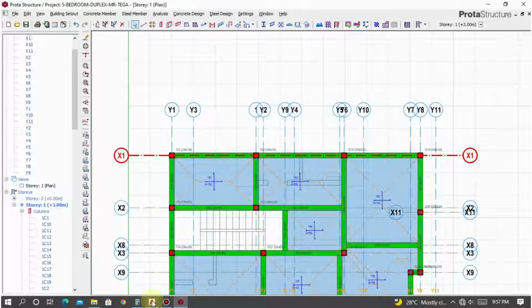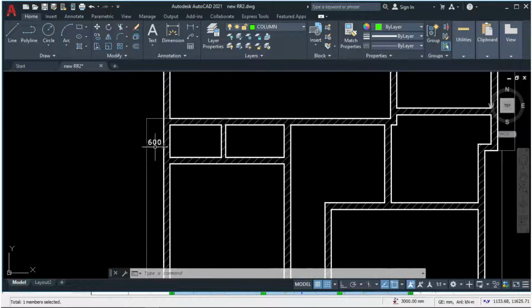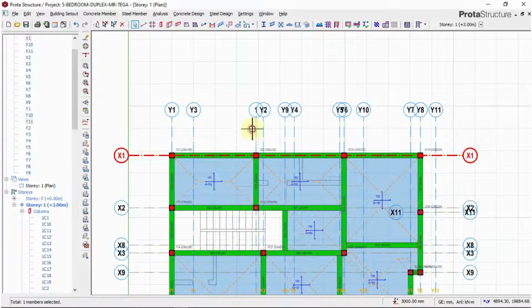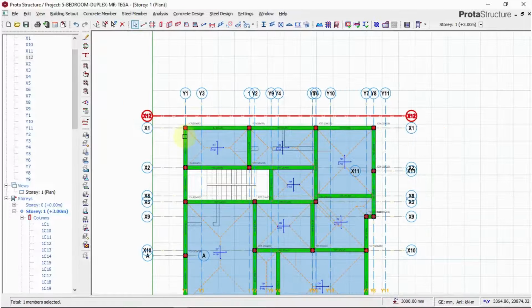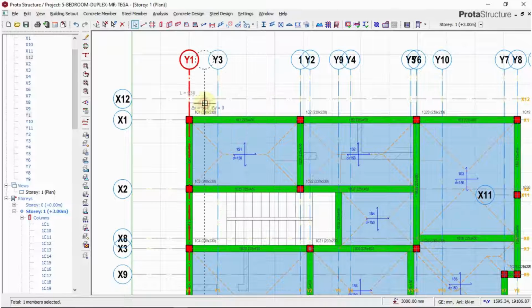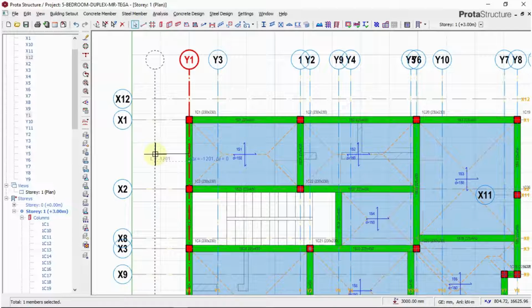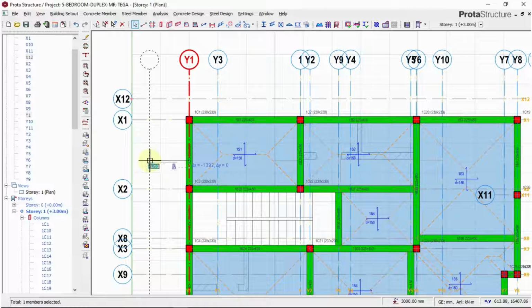We have the cantilever at this back, as you can see here. We have it at this back. We have it on this area also. We have it almost at every face. So we'll offset this again. I'll press my F2 key and 713. We are going left. So since we are offsetting on the left hand side of the screen, when you press your F2 key, you have to put minus 713, sorry, then we'll press enter.